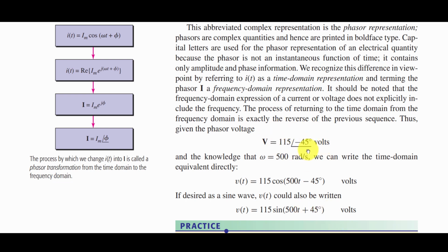And this thing has e to the power j omega t written to it, so that means that it has a magnitude as well as a direction, and by direction we mean it is rotating in the counterclockwise direction. That's why we represent these phasors, even though they are rotating, using vector representation. And we can use vector algebra and vector analysis to figure out the addition and subtraction of phasors, and multiplication and division of phasors.